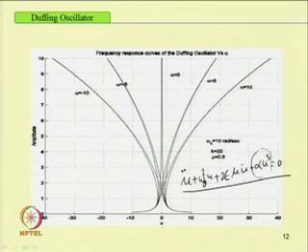Here sigma represents the detuning parameter and this is the amplitude. So, the amplitude depends on the frequency of the system. With change in frequency of the system, we have observed that the amplitude of the system also changes. This figure shows the amplitude and detuning parameter for different values of alpha, for alpha equal to plus and minus. This is for plus 10 and this is for minus 10. For alpha positive, the system contains a hardening type of spring, and in case of alpha negative, one can have a softening type of spring.